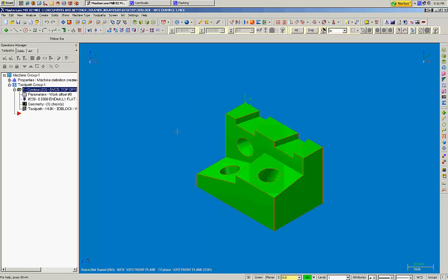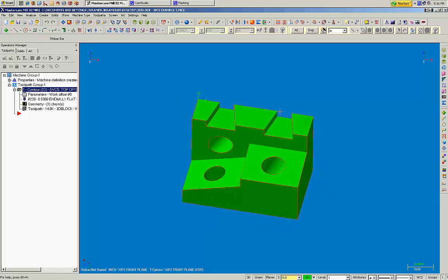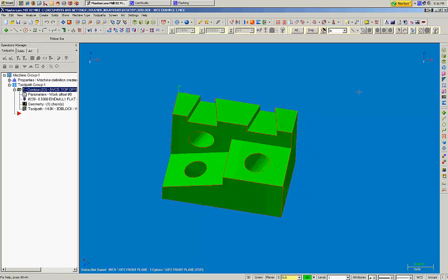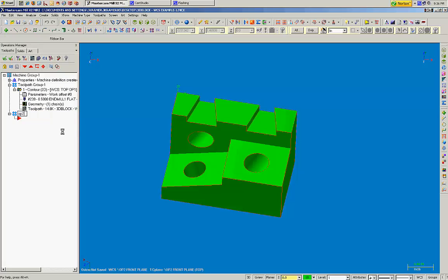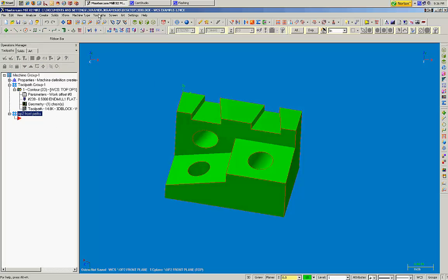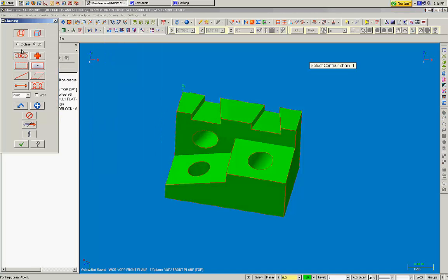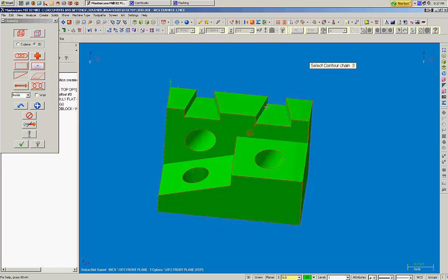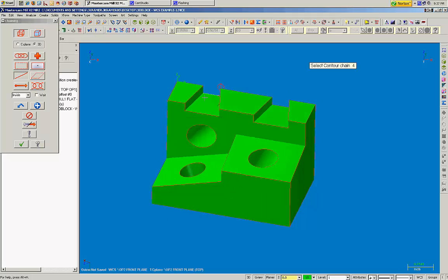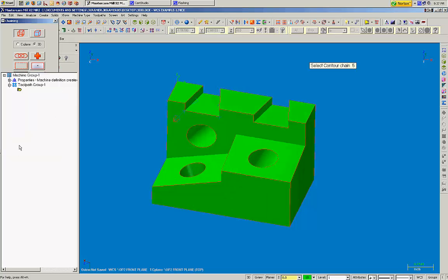I'm back in isometric. So in this case, now I can go ahead and pick some tools to actually run some paths through here. So we'll create ourselves a new selected program group, toolpath group right here, and we'll say up to front paths. That, and we'll go ahead and toolpath and contour, and in this case I'm going to use a single. I'll use this face, this edge here, this edge here, this edge here, and that edge there.